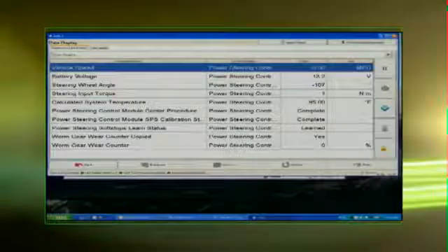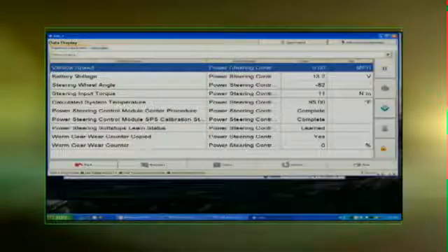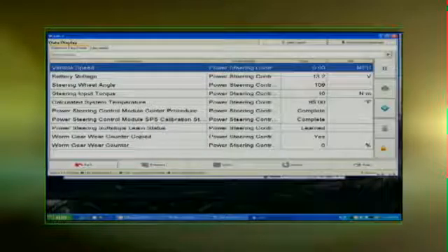Now what we're going to do is, just for grins, let's see if this thing works with the key on, engine stop. Go ahead and turn the wheel and see if we see a PID change, and tell me, go ahead and shout out here to me in the front of the car, does it feel easy to turn or is it hard to turn? Hard to turn. It is hard to turn, so we're waiting till an engine run signal for it to work.